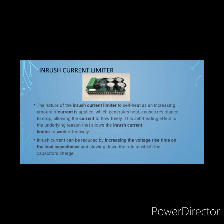Next is inrush current limiter. The nature of an inrush current limiter is to self-heat as an increasing amount of current is applied, which causes its resistance to drop, allowing the current to flow freely. The self-heating effect is the underlying reason that allows the inrush current limiter to work effectively. Inrush current can be reduced by increasing the voltage rise time on the load capacitance and slowing down the rate at which the capacitor charges.